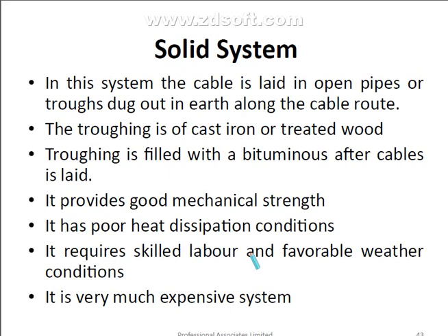So, solid system: in this system the cables are laid down in open pipes or through a dug-out in the earth along with the cable route. They are troughing in cast iron or treated wood. The troughing gear is fitted with a cover after the cable is laid. It is provided with good mechanical strength. It has poor heat dissipation.